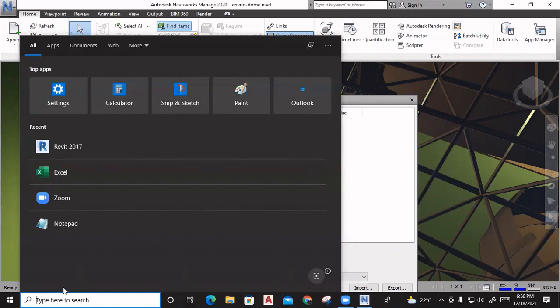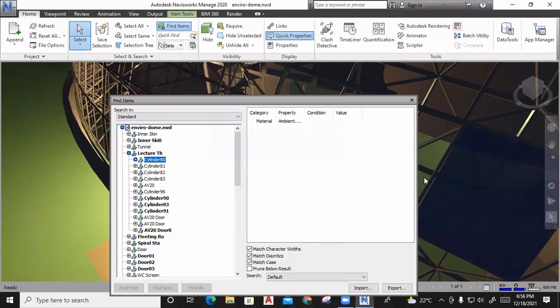Yeah, some kind of rule-based filter, like selecting a particular wall, and we right click with the mouse, and there we have filter by elements, filter by category. In that we are going to give the rules, some equations. So the same equations we are going to follow here: not equal, equal, greater, lesser. We are going to select whatever we want and give the value, how much till the range, what range you want to select. Then you can export it or import it.